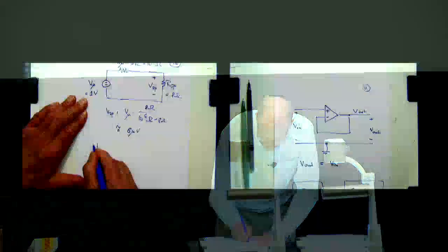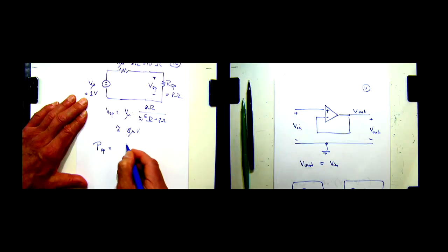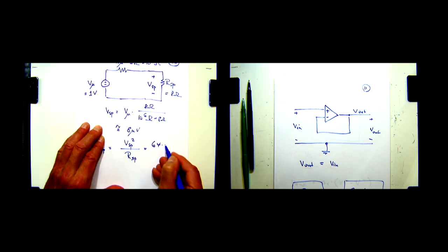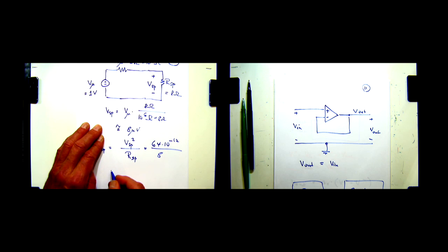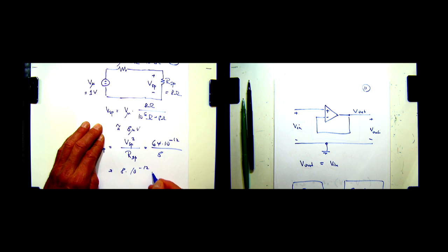Do you think you're going to get a lot of sound out of that speaker? In fact, could we figure that out? Well, what is the power of the speaker? Now here it would be useful to use this expression. Because we don't know the current, we could calculate it, but we just use Ohm's law in this equation. So V speaker, 8 micro, so that's 64 times 10 to the minus 12 divided by 8. So that's 8 times 10 to the minus 12 watts.